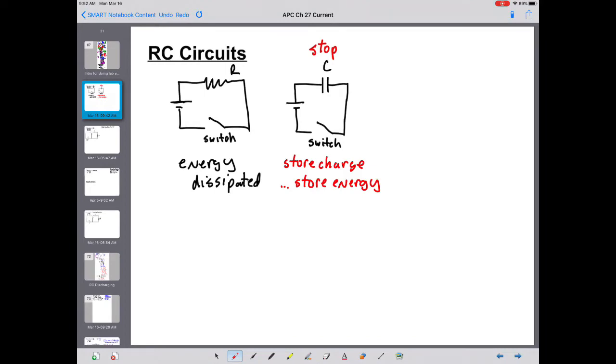Now, when you have just a capacitor in your circuit, when you first throw the switch, there are no charges on the plates of the capacitor. So then charges will rush out, in large quantities to the plates of that capacitor, which means you would start out with a very high current. So initially that current spike can heat up wires, damage things in the circuit.